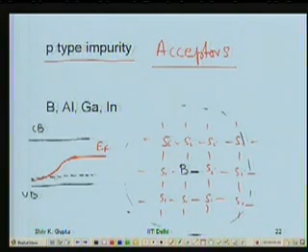So now these impurity levels which are present here are accepting electrons from the valence band. This energy is very small again. Boron is accepting the electron and thereby getting ionized. Phosphorus has given out the electron and got ionized. This is accepting the electron and getting ionized.